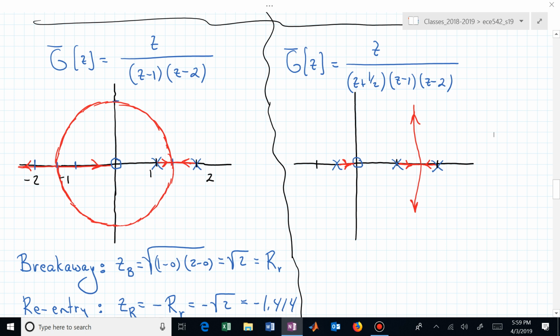We're going to see that what happens for large values of k is that these basically split the z-plane symmetrically, and the first angle of that upper branch is going to eventually approach an asymptote that has an angle of 90 degrees, or 180 degrees divided by the pole zero excess.